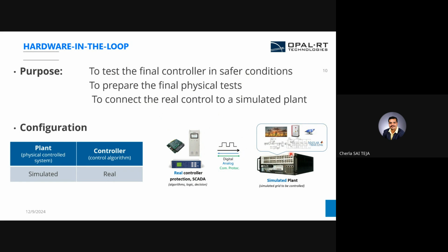As the plant is simulated, we need not worry about what will happen during fault studies. Let us say I have a motor controller. If it is a physical motor and I want to short a phase on the motor, we all know it will result in hazardous situations. But in hardware in loop testing, as the motor is simulated, we can happily do fault studies on the plant and see the control response. So this is where hardware in loop testing finds a wide range of applications in our studies.